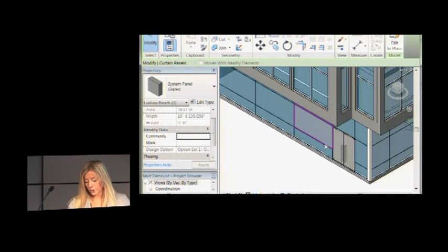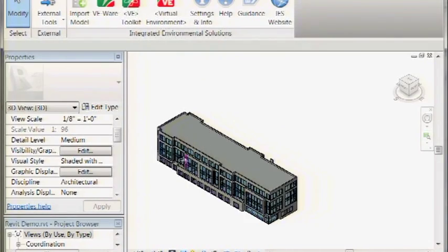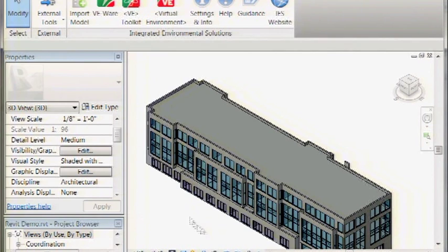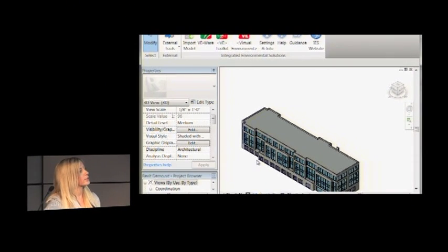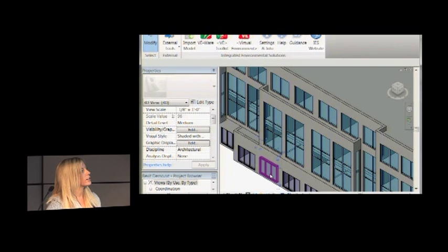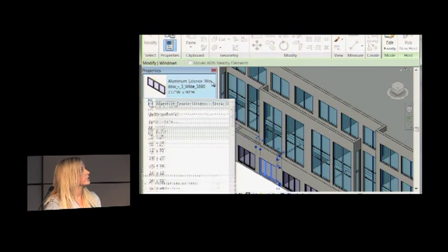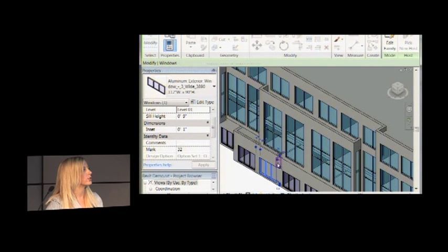Finally, just to go over external holes. A very common thing you'll see for architects is if you have a porch or an atrium space or something that is a covered area, there'll be a room inside of it. And what they do with it is, instead of having a window here, you have something like an opening. These are all windows, but just an opening in the space. So a hard thing to resolve with this is IES does not have external holes.